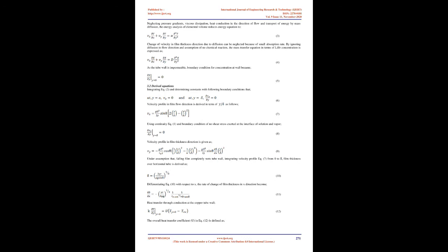Exposed surface area of the film and time of exposure at the interface are critical for absorption of vapors and influence the number of redistribution positions. Hence, for illustration purposes, 4 redistribution positions symmetrically placed at 30° and 60° have been selected, Fig. 3. Properties of solution were referred from the ASHRAE Handbook of Fundamentals [13].